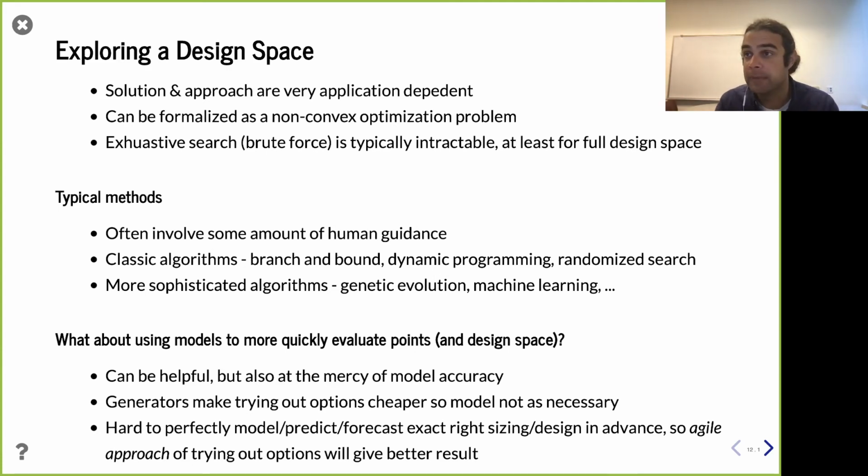And so the question that came in from chat is, oh wait a second, these models sound pretty helpful. Isn't it perhaps easier to use these models to explore design space than actually writing Chisel to do that? Definitely, if you're doing a model, an analytic model, statistical model, however you're doing it, it's easier to change a model than it is to change a real design. That's simple. However, Chisel is easier to change than changing Verilog. And so if I was in charge of a company, what would I do? I would do all of the above. I would have people doing some early analytic models to see what's even worth doing.